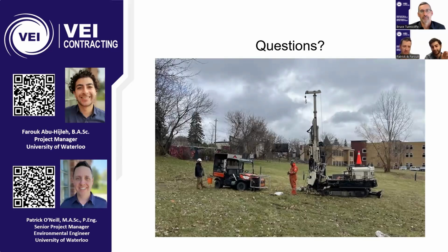I would recommend in a perfect world, do the HPT first, find your conductive seams throughout the site, and then install your wells because the geoprobe's on site already. So install your wells, and then you're testing the most important points of interest for the site. Think of it as a supplemental addition to your investigation. It's not necessarily here to replace slug testing. Not yet. We'll see how the dissipation data grows over time.